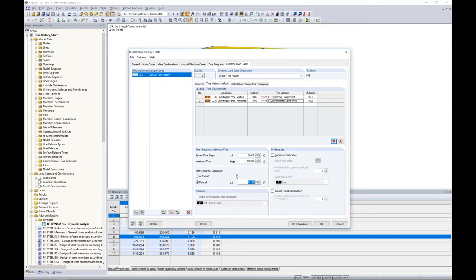So way back in the PowerPoint, I had mentioned a suggestion of a time step equal to or less than 1/20 times our period. Now remember, the frequency is the largest frequency from either the excitation or my natural vibration analysis. In our case, this was exactly the same at around 25.8. So this comes out to about 0.001 seconds.